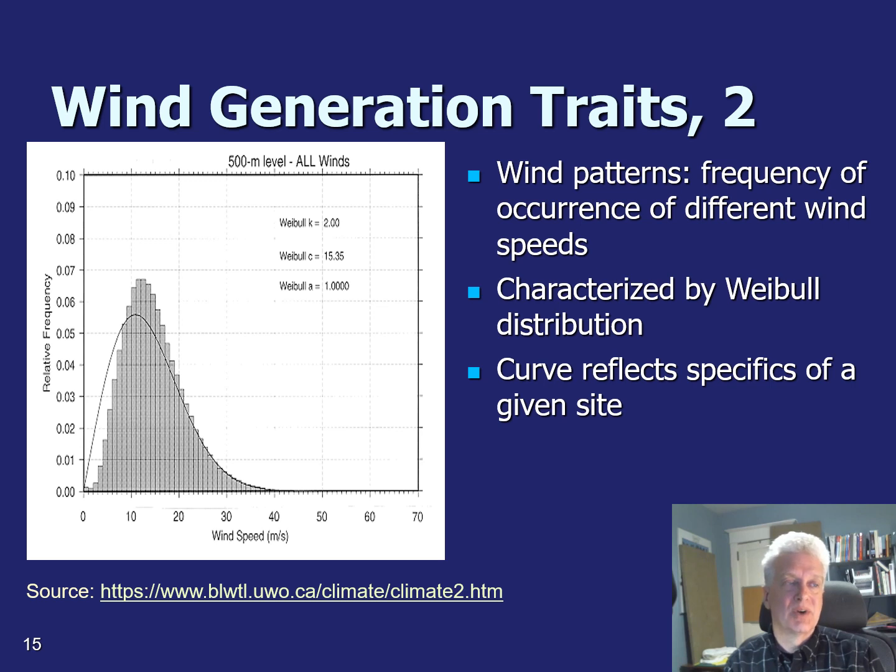And so statistically you get this: the wind speed is never really quite zero. You'll see on this one that it's very close. It's rarely down at the first bin there, and there's always a little bit, and then there's often a little more. Then less and less often there's very, very high winds. So the shape of this curve reflects the characteristics of a given site, and you can generalize this with the equation for the curve shape that's known as the Weibull distribution.